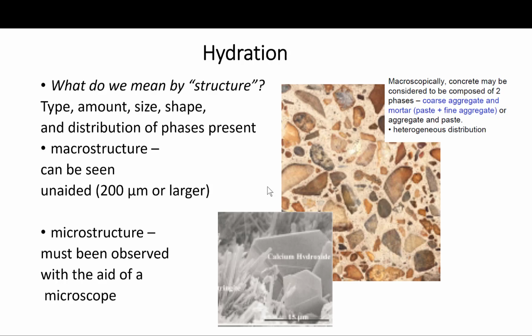The limit of resolution of the unaided human eye is approximately 1/5 of a millimeter, about 200 microns. The term microstructure is used for the microscopically magnified portion of the macrostructure. The magnification capability of some of the modern electron microscopes is on the order of 10 to the power 5.